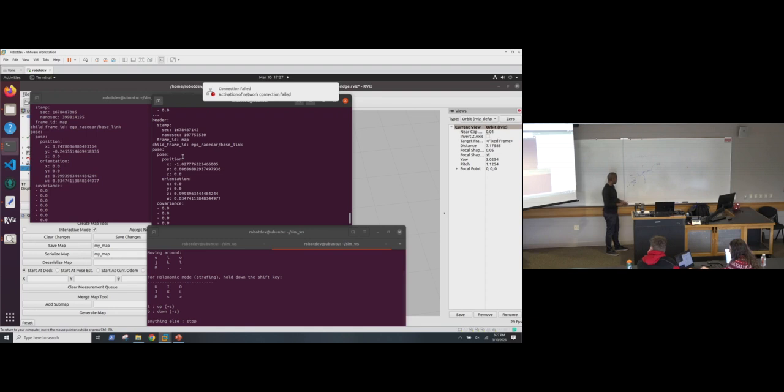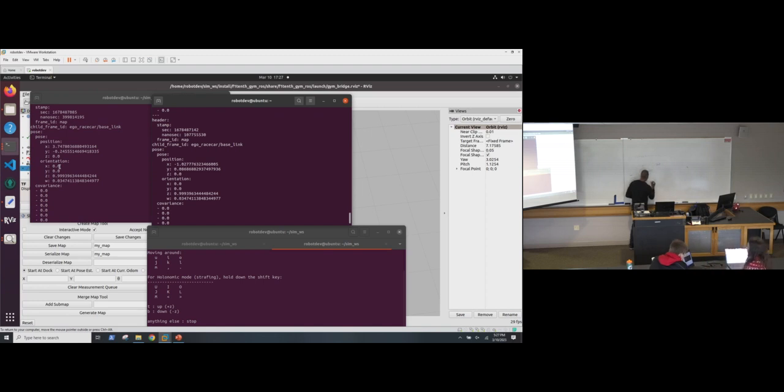Okay, that makes sense. So the position X, Y, Z, I get what that is. What's the orientation? It is a vector, but it's a quaternion. It's representing roll, pitch, and yaw, as it's easier to do that mathematically as a quaternion. It's going to have an X component, a Y component, a Z component, and a W component as a vector.